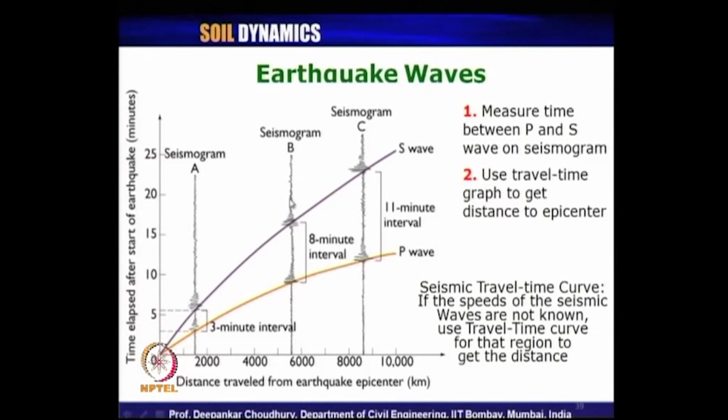The 3 circle method and the distance formula that I have explained and wrote, we can use provided we know the typical crustal velocity of P wave and S wave very accurately. If it is not exact, then we may get erroneous data.